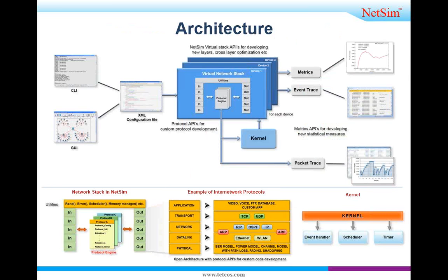Now, the architecture of NetSim software. It will give you a view of NetSim. Here, a user will design the network and configure it in the GUI interface, which will be simulated by the NetSim engine and thereby provide multiple metrics regarding the performance of the simulated network. The user is not required to write any script or code while designing and configuring the network scenario.